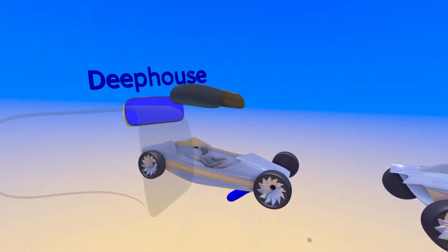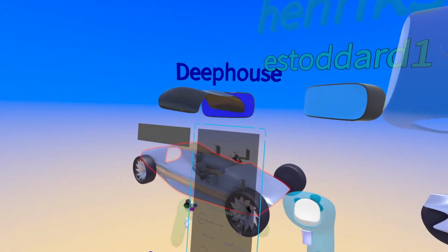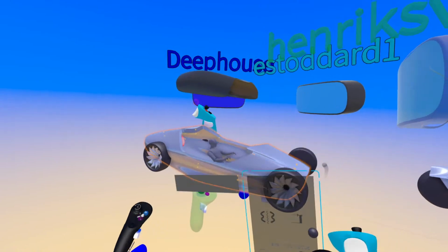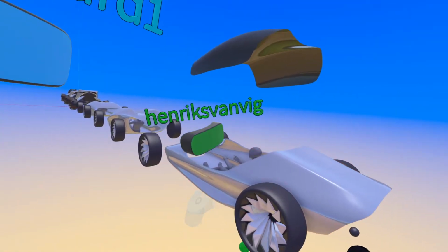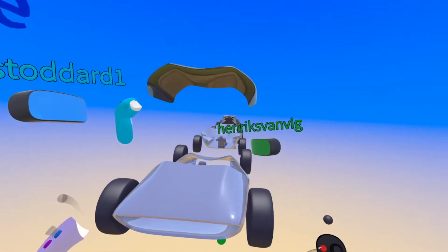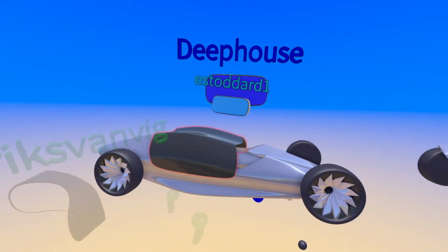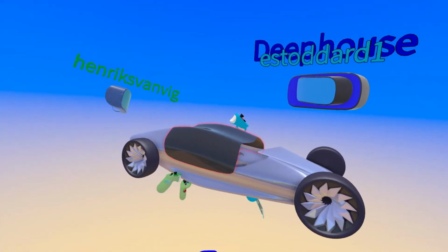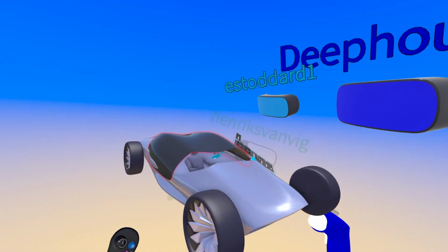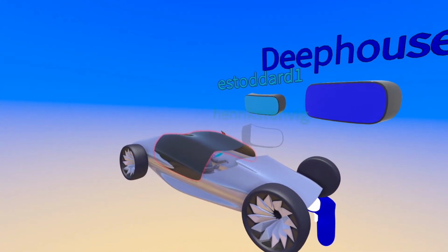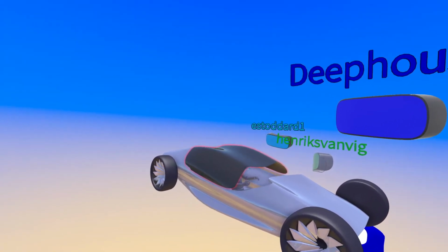I wanted to show you just the thicken tool. If I take a subdiv surface and go to edit mode, I can add thickness to it, which comes in really handy when I want to do glass and body separation, because now I can just take the glass down, and I don't have to worry about perfectly matching the glass to the body, because in a real car the glass is always slightly offset from the body.